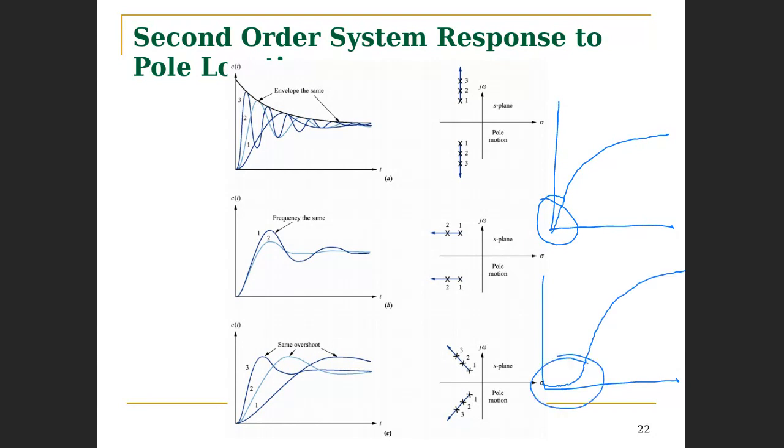So this is what distinguishes it. If you look at a system response that resembles a first order system, take a look at the initial point. If it is moving with a very sharp gradient, then it's first order. If it has a lag, like what we're seeing here, this slowness, I'm trying not to use the word lag because I didn't define lag.